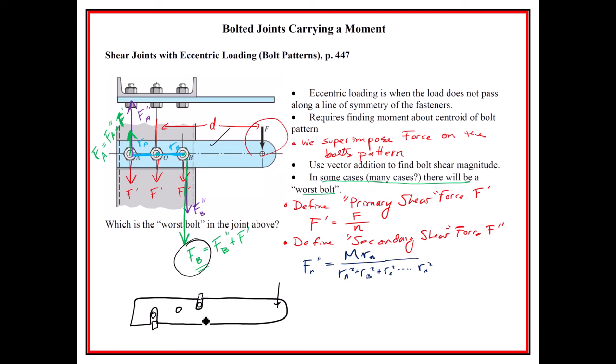and we would take it against the areas that would end up like right in there. We'd also take, if we want to find the shear stress, we would take it across the bolt and take the F, and this would be the area of the bolt, and then we would get the bolt shear stress.